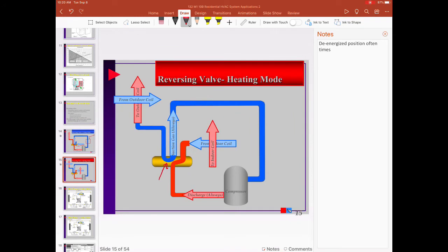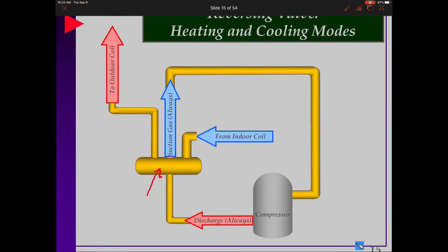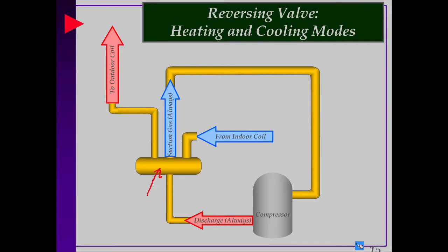Now in this particular slide, I'm going to animate this one here so you can see what's going on with it. And on this particular one here, we're showing a compressor operation. So we're going discharge line. We are sending that directly to that single lone port, and then we're going to the outdoor coil. So right now we are in the cooling mode in this particular case. When we